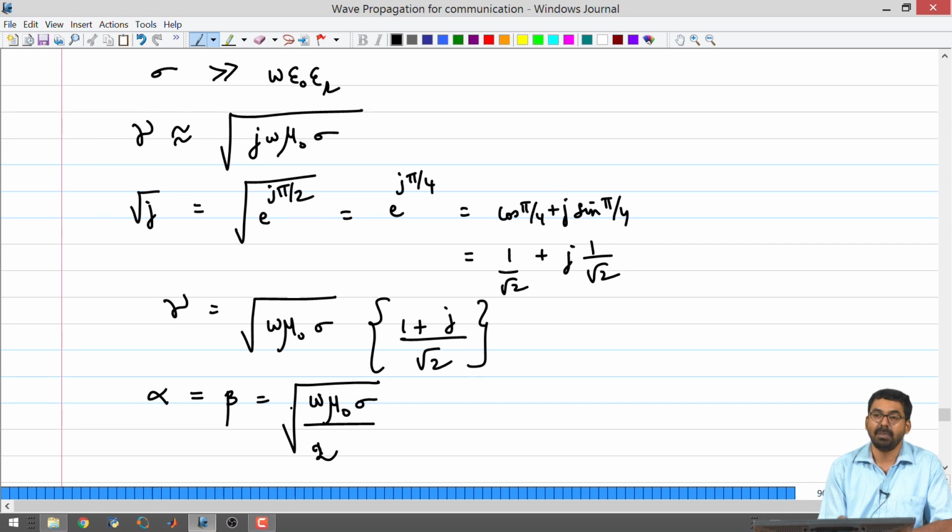So at higher frequencies you will experience higher attenuation in conductive media. At higher frequencies the phase constant is also higher, that means the wave will go from 0 to 2 pi much faster than what it did in vacuum. These things become clearer if you start making some assumptions, scratch out terms and look at a simpler expression.